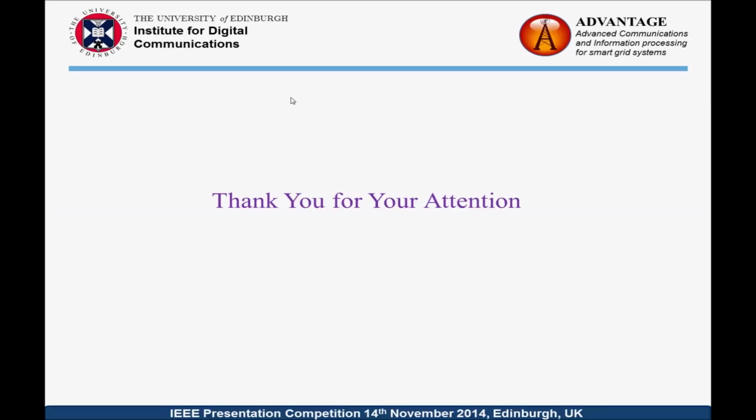I should divide the communication into different parts. The first point is wired versus wireless. In wired communication, yes, in many cases we can achieve this high reliability, and right now they have it. But the problem comes when we are using wireless communication. Exactly because of that, many of the cellular communication companies providing this facility cannot guarantee this ultra reliability in wireless systems because of the expense. Because of that, we focus just on special real-time signaling and control systems. We cannot provide this highly reliable or ultra reliable communication for all of the smart grid.